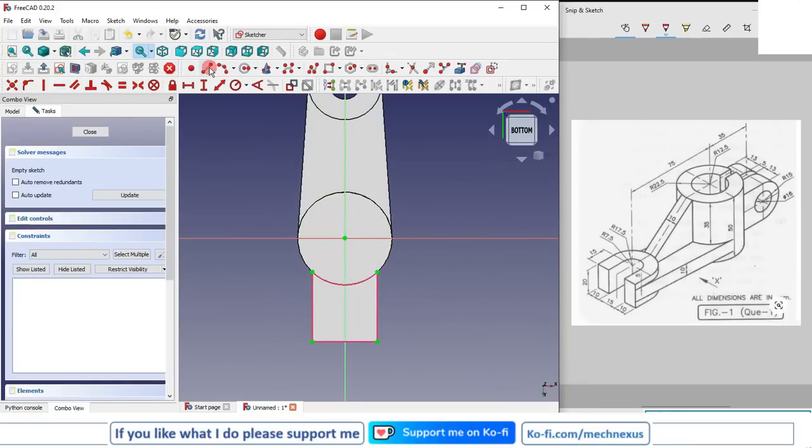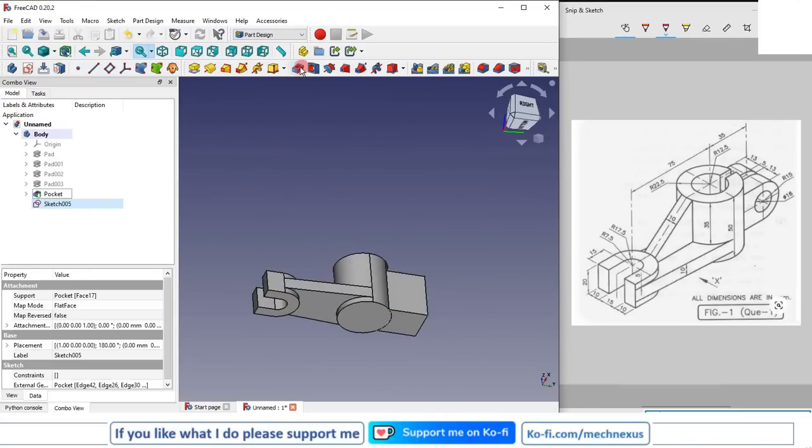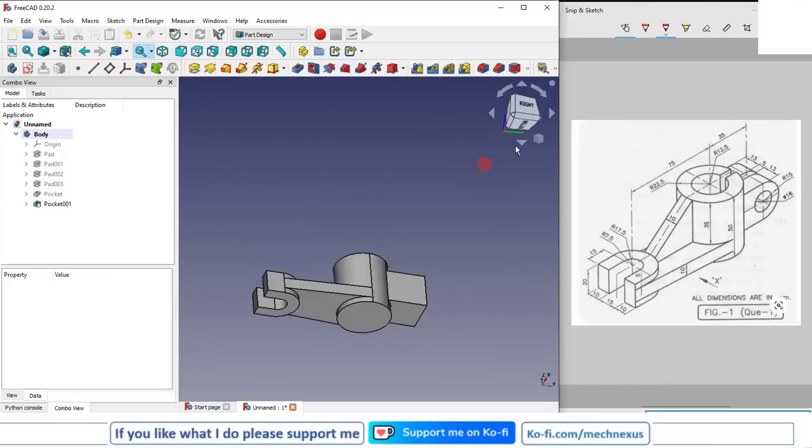I will close the profile. Select the 3-point arc. Now I will again go with the cut, and I will give my cut depth 10 mm, and I will say OK.